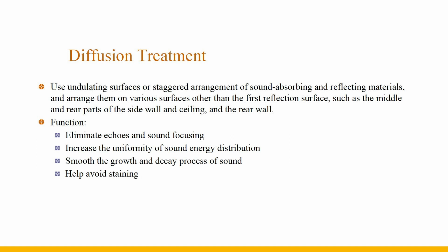Acoustic coloration refers to the spectral change caused by the superposition of strong reflected sound and direct sound, resulting in temporal distortion. The diffusing effect of a contoured diffuser depends on the size of the diffuser and the wavelength of the sound waves. The size of the diffuser must be comparable to the wavelength of the sound wave to have a diffusion effect. By designing diffusers of different sizes and shapes and arranging them irregularly, the diffusion effect can be achieved in a wider frequency band.